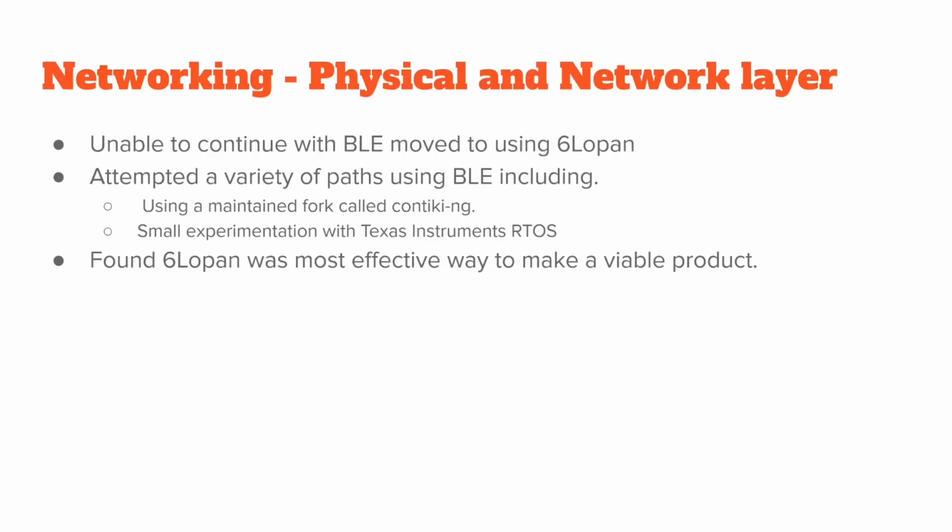For the networking physical layer, we originally tried to use Bluetooth, and we did a lot of experimentation. The original path was using a fork of Contiki called Contiki-NG, which is a maintained version. It has an experimental Bluetooth driver for the sensor tag. But it's more a mesh network, and we weren't able to get it working to our level of satisfaction. And how it's implemented in the new version of Contiki-NG is it still requires an edge router.